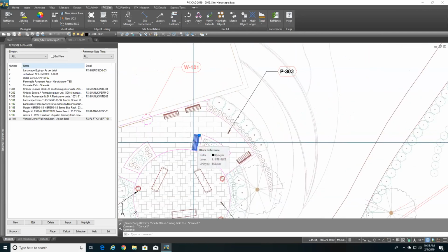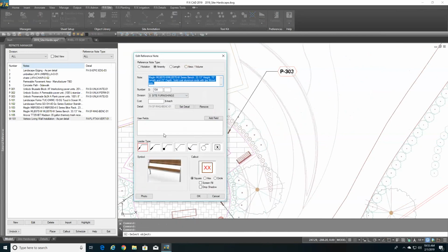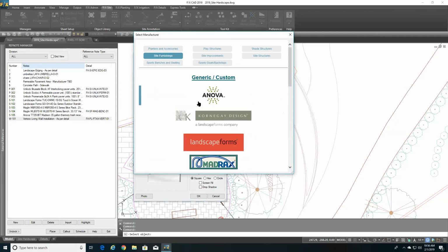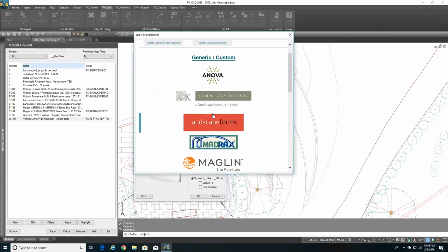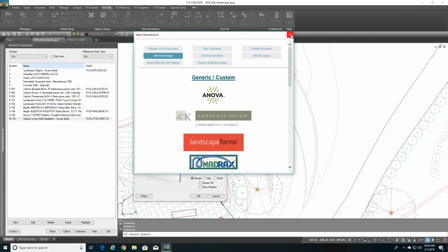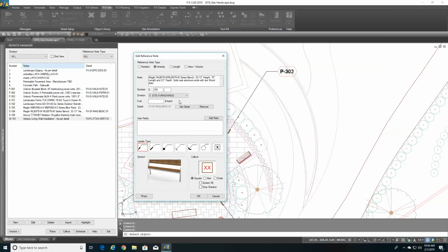That edit objects next to the match tools. Oh yeah, I didn't actually highlight that. But yeah, if you guys ever want to change or edit that object, or even change it to another actual object or a product, you can hit that symbol and it takes you immediately back to the manufacturer selection dialog, right? So you can start that process over again if you need to change all instances of an object, or even just the one. But yeah, adding a cost, let's say it's 500.